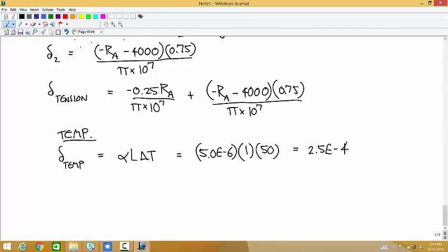Question for you. I know, like, from experience, that when the bar is twisting or you put some force on it, it starts to heat up in some way. I know that the change in temperature shouldn't be that great, but should we take that temperature into account? As long as it's in its elastic range, that shouldn't happen. I think what you're talking about is once it goes into its plastic range, then it starts to convert.